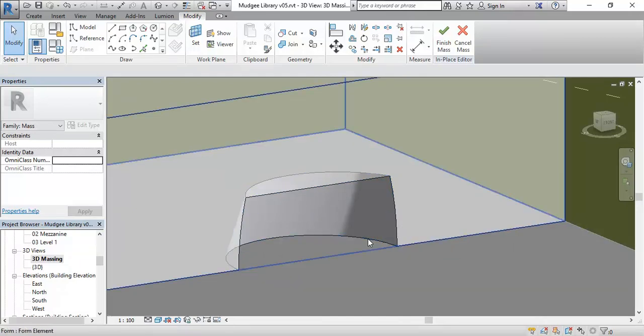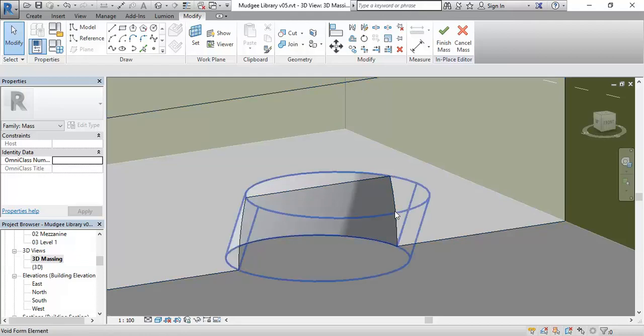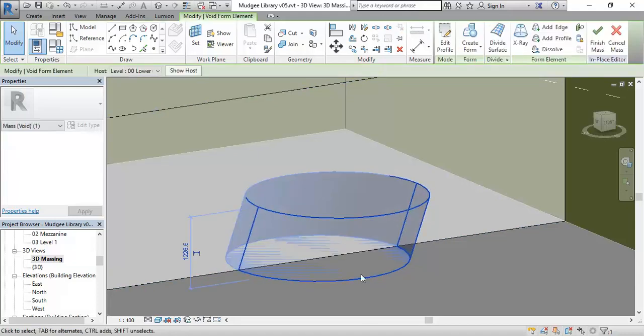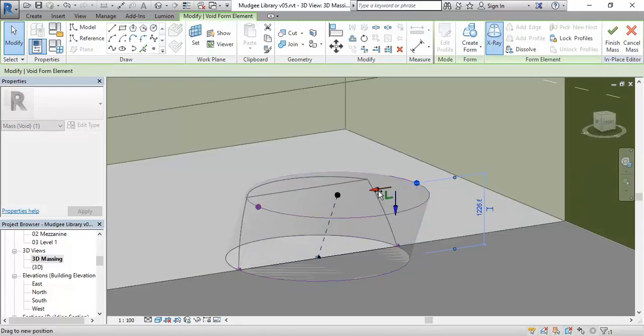So now to go back to the original void, you can see that I'm just going to the edge that the void is creating. So any edge there, whether it's inside there at the bottom or the top, or these side parts, they're all being made by the void. So if I move the cursor there, then I can use tab and just keep pressing until I get the void highlighted. Now I can select that. And so here sometimes it's helpful to make this X-ray mode, so you can see things a bit more clearly. And then again I can use tab to get the different parts. So here maybe I'll just get that, see if I can get that vertex there on the top. There we are. And we can maybe look at some different options there.